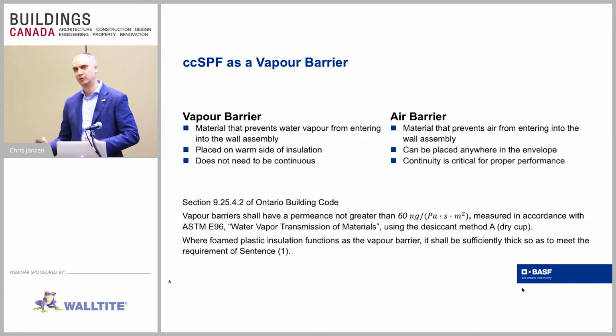But if you're relying on some of those components as part of your air barrier, that's where you need to have 100% continuity within the whole building, because if you have a little square inch of hole in your air barrier system, then that can allow moisture to drive through your wall assembly and get condensation in that wall assembly. And just one little area, that can be enough to cause a big headache for the homeowner and have to go back and work on stuff.